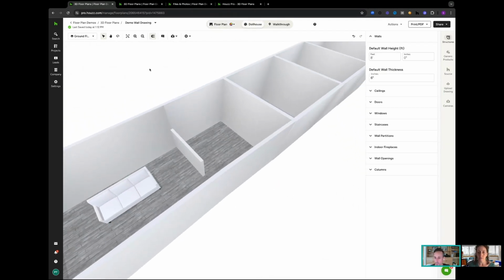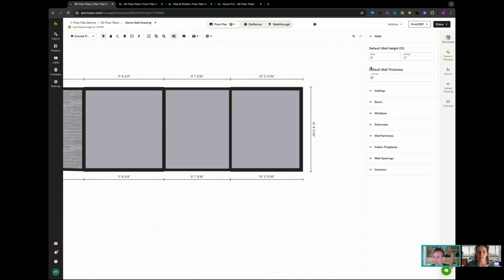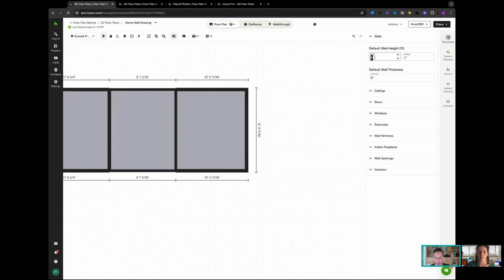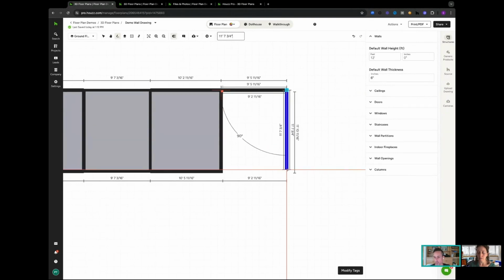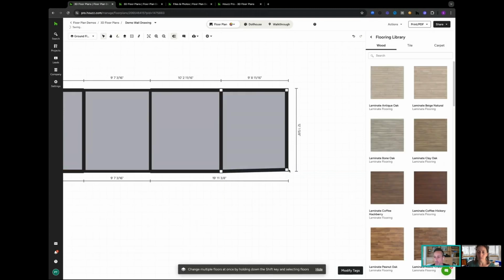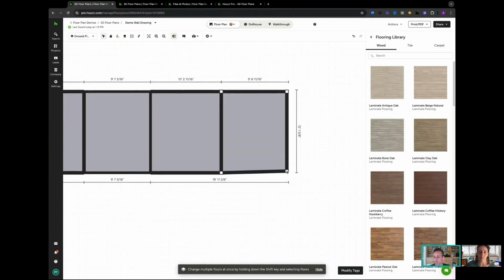One more important aspect is the wall height. That will work similar to the wall thickness. If you want to start drawing a taller wall, let's say a 12-foot wall, you can put that in. Now the next wall that you draw will be a 12-foot tall wall, and it's still at the 6-inch mark. So it's quite a thick wall.